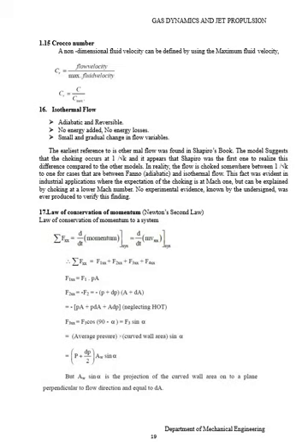So therefore, summation of x force is equal to F1x plus F2x plus F3x plus F4x. F1x is equal to P A. F2x is equal to minus F2, which is minus (P plus dP) times (A plus dA), equal to minus of (PA plus P dA plus A dP), neglecting higher order terms. F3x is equal to F3 cos(90 minus alpha), which is F3 sin alpha, equal to average pressure into curved wall area into sin alpha, which is (P plus dP) divided by 2 times Aw sin alpha.